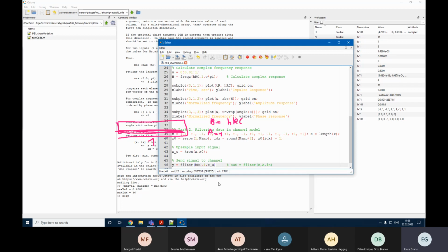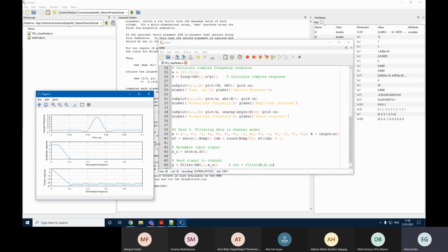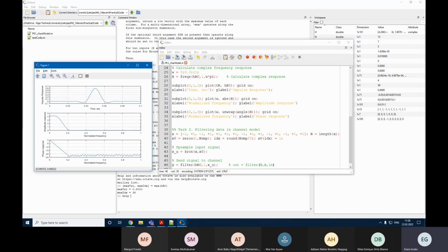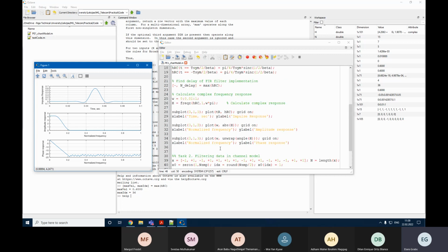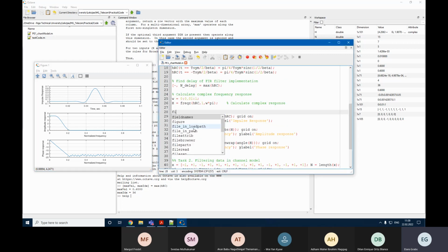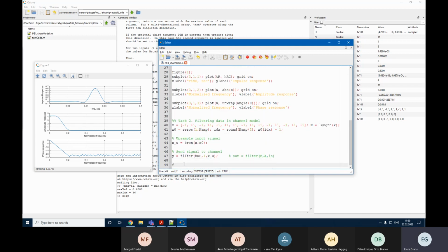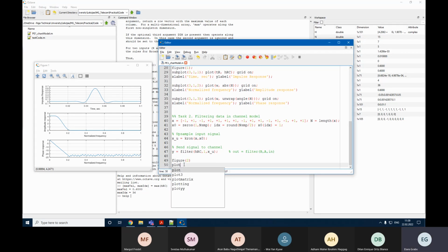So now we can plot this signal, but in order to have a new window for figures, because currently we already have many figures here, and furthermore these are related to filters, and the next window will be related to the signals, we need to make figure windows like this. Here, for example, we are going to have figure 1. Then here we are going to make figure 2. And accordingly, let us plot our signal y without the x argument, just to see how it looks.